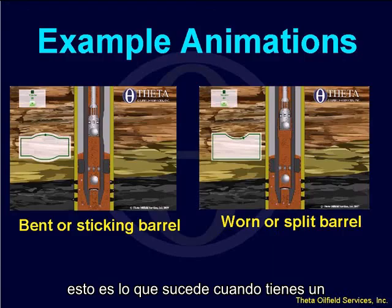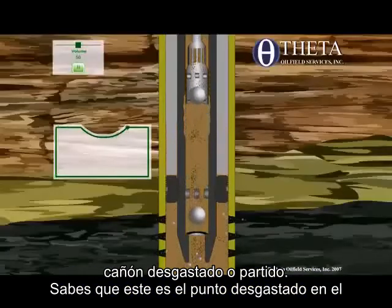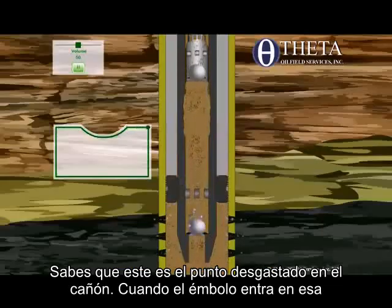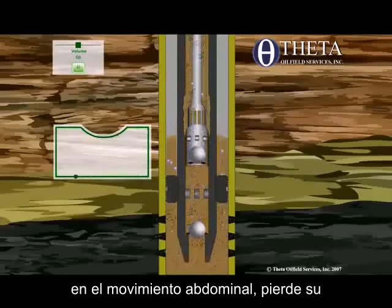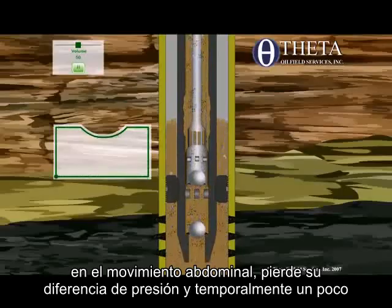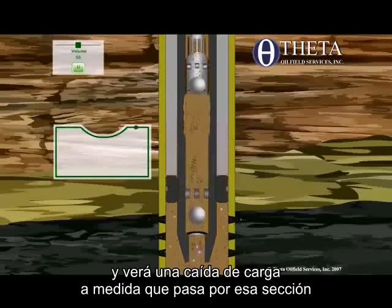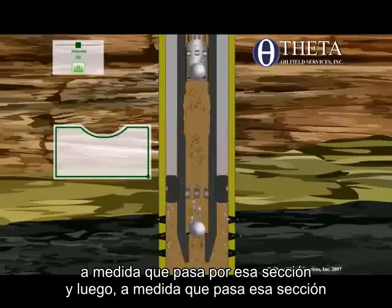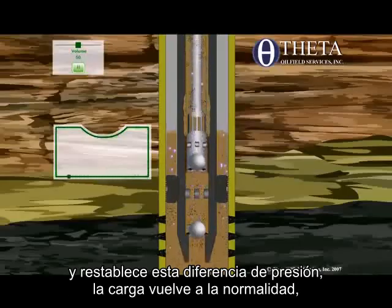This is what happens when you have a worn or split barrel. You know, this is the worn spot in the barrel. When the plunger gets into that section, on the upstroke, it loses a little bit of its pressure difference temporarily, and you're going to see a drop in load as it goes through that section. And then as it goes past that section and reestablishes its pressure difference, then the load goes back to normal.